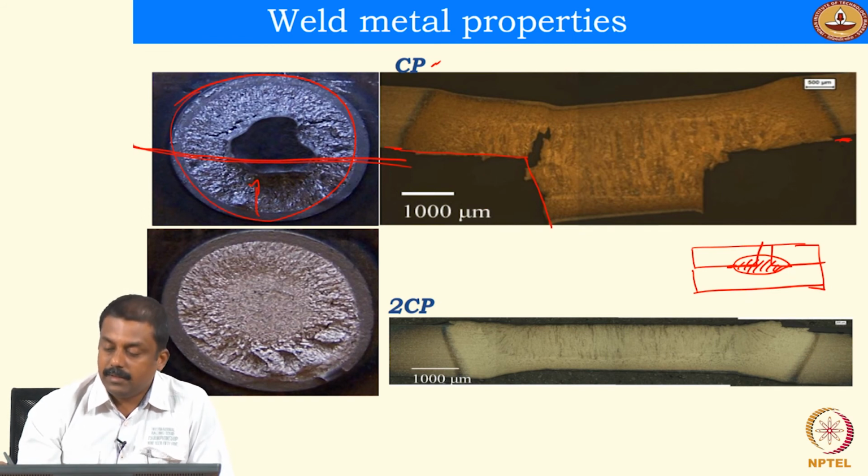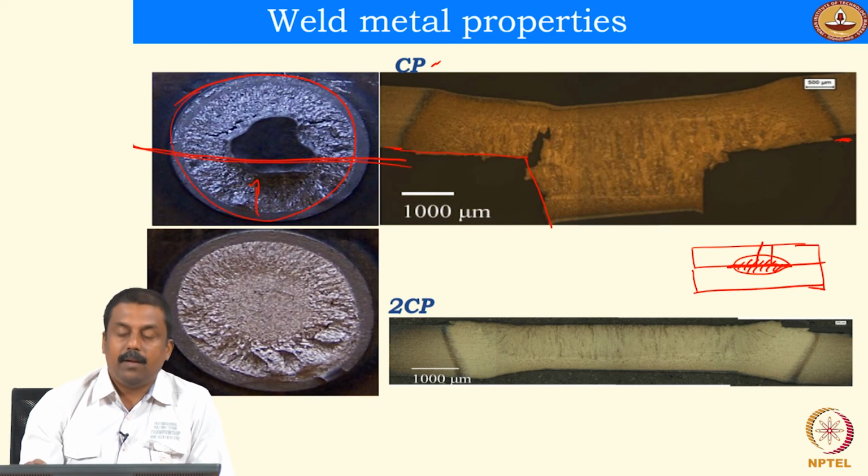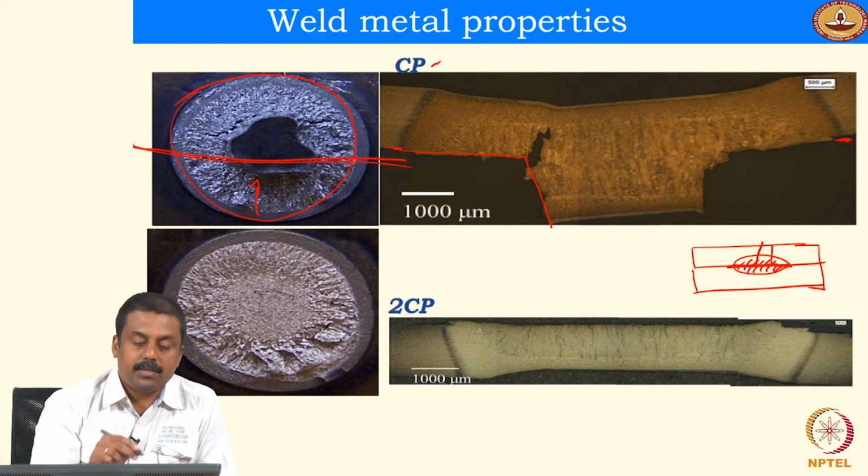This center line is the last solidifying region in resistance spot welding. So obviously you will have a segregation of phosphorus and carbon along this weld center line. When you have a brittle weld center line and test it in tensile testing, as I explained in the previous graph, a crack nucleates and follows the weld center line and subsequently fails along it, leading to a partial plug failure.